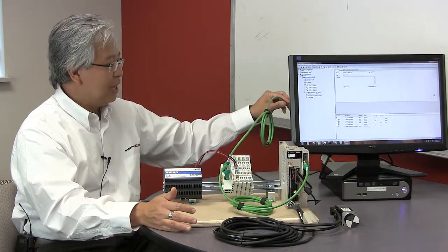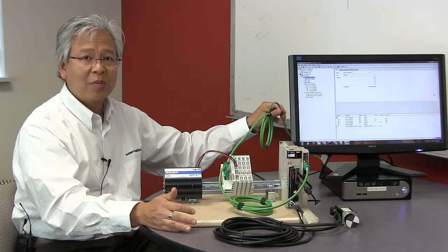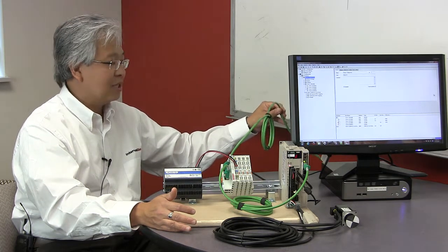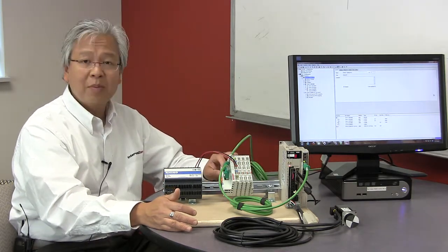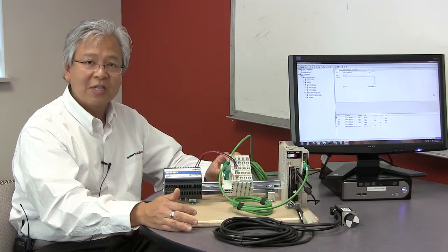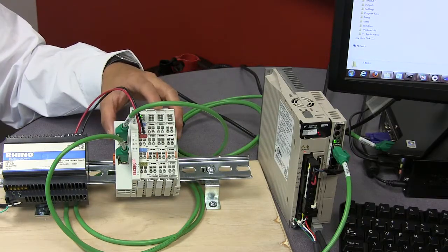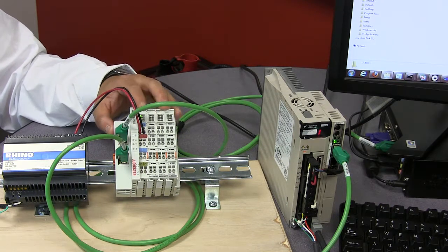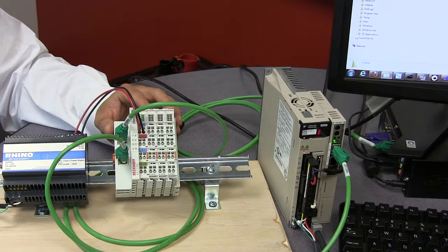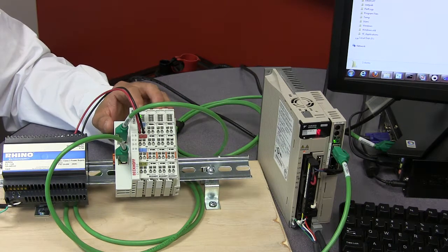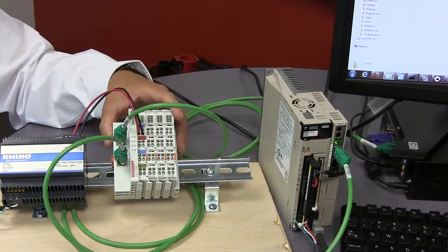If you see here, one of the benefits of EtherCAT is that we're able to use standard Ethernet hardware. There's no proprietary cabling. This is just a simple Cat5 cable coming out of the PC and into the input port right here of our first EtherCAT module. So we have one cable coming here. Here we have just a couple of input and output modules. EtherCAT is very expandable. This bus can be expanded up to around 65,000 nodes, so it can definitely scale to some very large applications. Here we just have a couple for this desktop example.